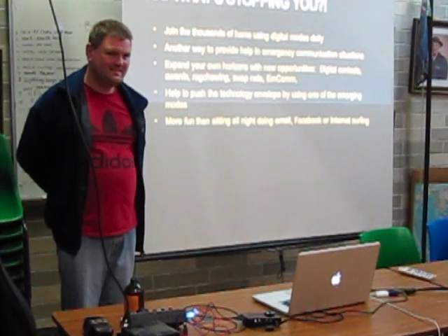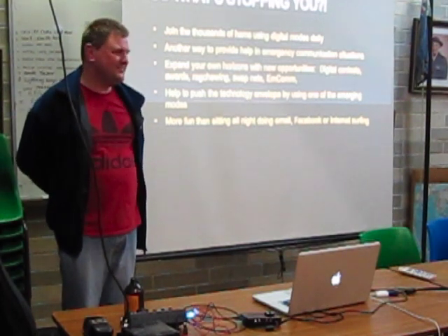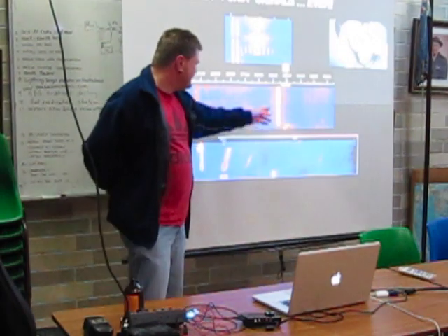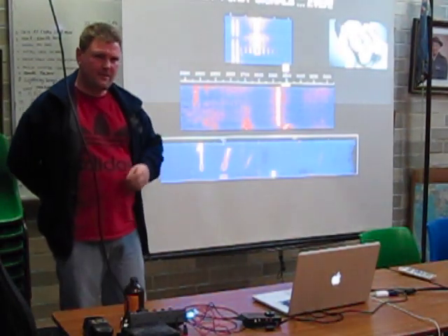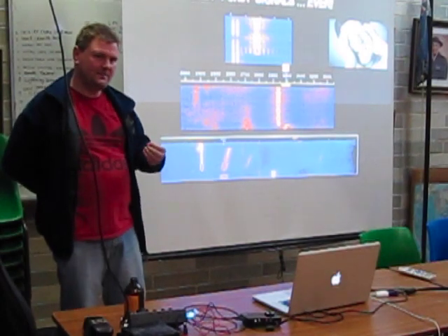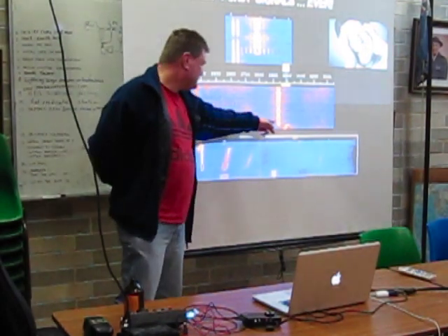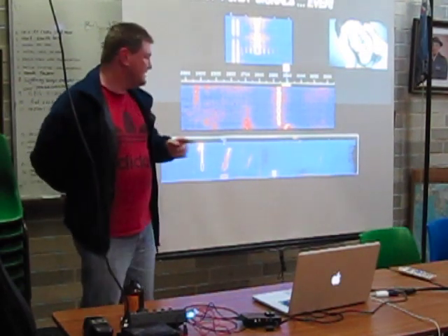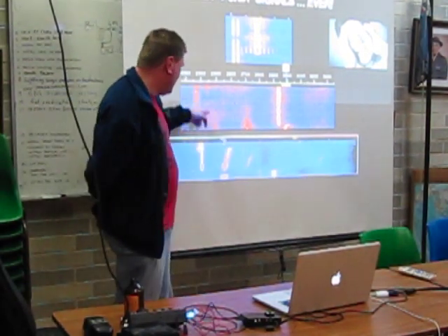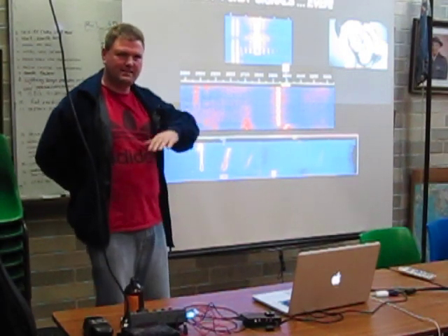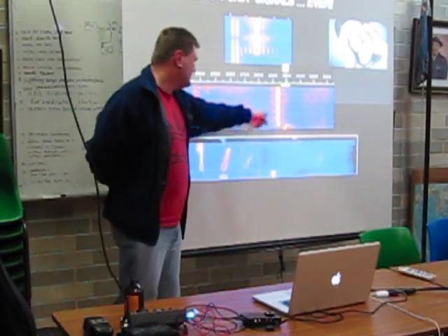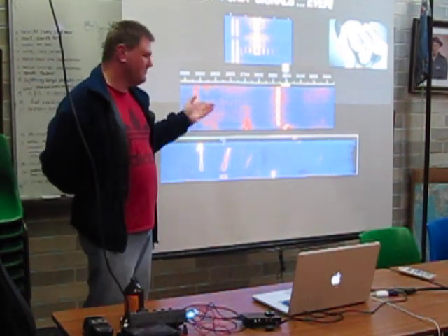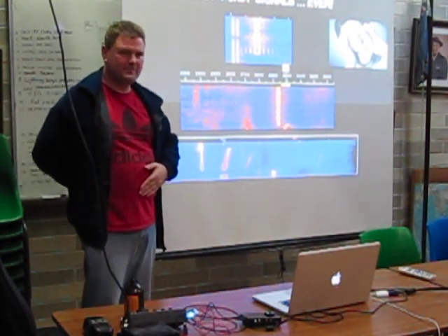You're always going to get that. The problem is, if one person transmits a very powerful signal, much more powerful than everyone else, what happens in your receiver is it activates your automatic gain control. And so now, if there are any weak signals, you won't hear them because the gain of your receiver has been wound back because of the strong signal. So it's considered quite impolite to run kilowatts of power on some of these modes.